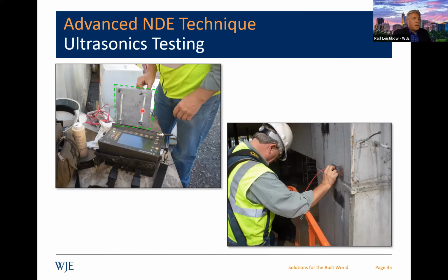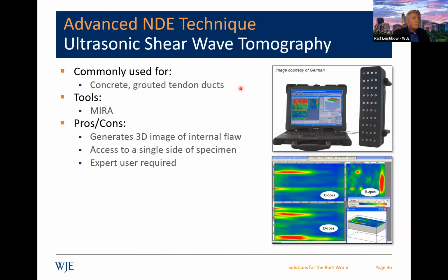Obviously that impacts the capacity of those embed plates and the stud orientation. So we were able to use the UT to determine the approximate range of angles of the headed stud. That was interesting to do non-destructively, and we verified that. It was a neat way to use this equipment as well.